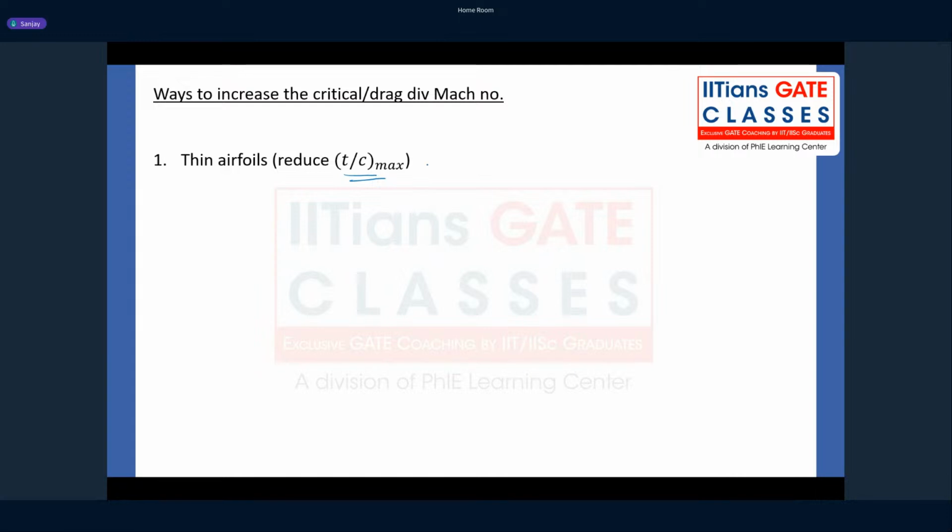But if I consider this option, can I make the aerofoil as thin as possible? Can I make it very, very thin? Can I fit that into an aircraft? Can I make wings of very, very thin airfoils? If I do that, what will happen? Of course, I will get a very high critical Mach number, but is that a good option?